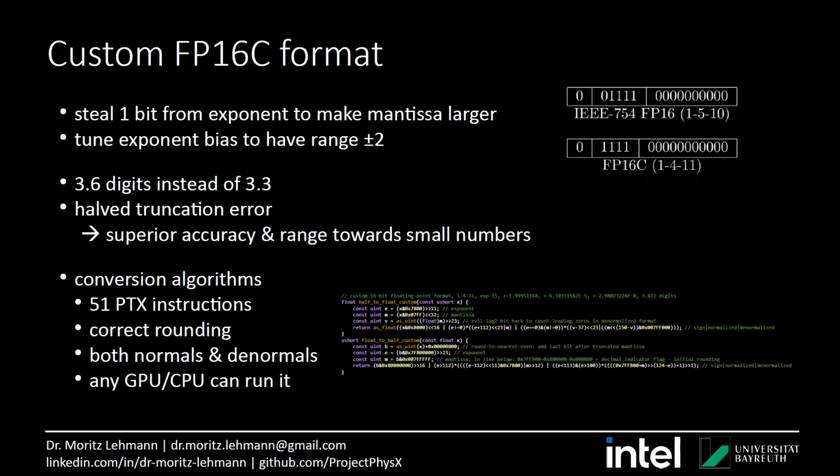The 16-bit memory compression reduces the memory footprint almost in half, and it has a second benefit. In every time step, you can load twice the number of grid cells per given time, because two grid cells fit in the same memory space, which means it also makes it almost twice as fast. Okay. Yeah.